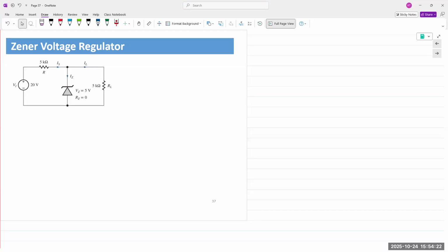As I stated earlier, we have rectifier circuits, and the output of a rectifier circuit is typically fed into a Zener diode, and the Zener diode is going to conduct and allow us to have a standard voltage at the output. Here's the thing, in terms of device physics, this is what happens. It conducts in the negative half cycle. So what is it doing? Junction breaks down. There's a huge influx of charge carriers crossing over the junction.